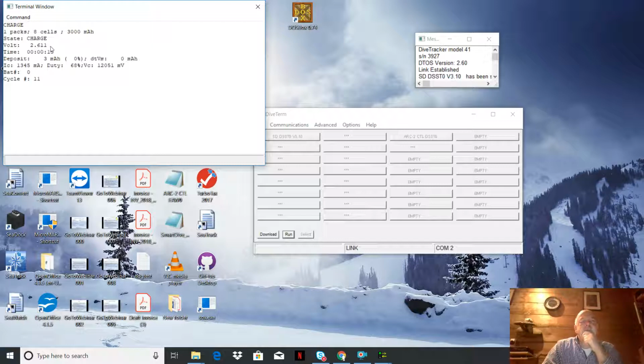Here now I'm seeing a voltage. The nominal voltage of these are 8 cells at 1.2 volts each, which is 9.6 volt nominal and really 12 volt once it's fully charged. This is averaged over 1 minute, so I won't really have a valid reading here until I'm at 1 minute. This is just so if you ever want to do that, you can monitor how your battery charging is coming along, such as if you are suspecting that you might have a worn out battery. Okay, we are now at 7.895, 45 seconds.